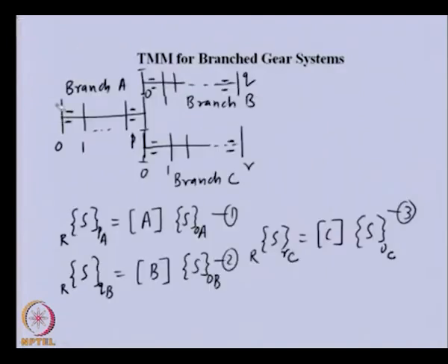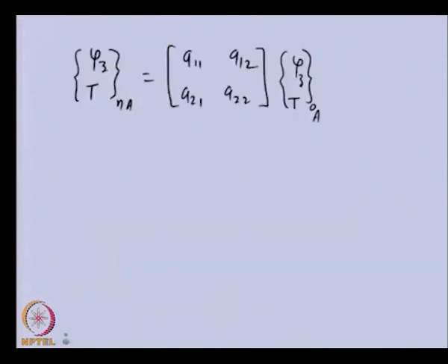So there will be torque 0 here, the displacement will not be 0, and for simplicity, because we are analyzing the free vibration, we are taking this particular station's angular displacement as unity, and we will obtain relative to this the displacements of the others. So we will equate this to 1, and this according to the boundary condition is 0.